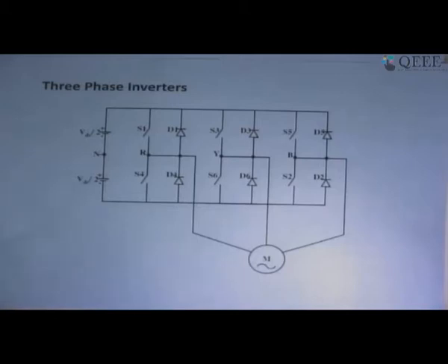The small harmonics because of switching frequency will be easily absorbed by the leakage inductance of the induction machine. This results in a perfect, almost DC torque on the motor shaft, and smooth running of the motor, which is good for the life of the motor.